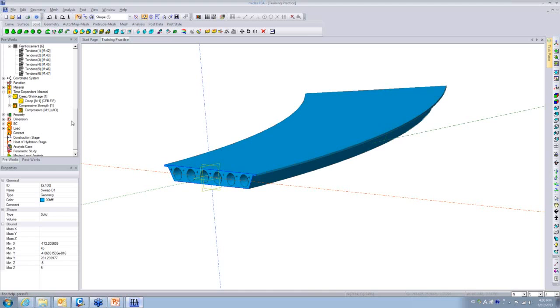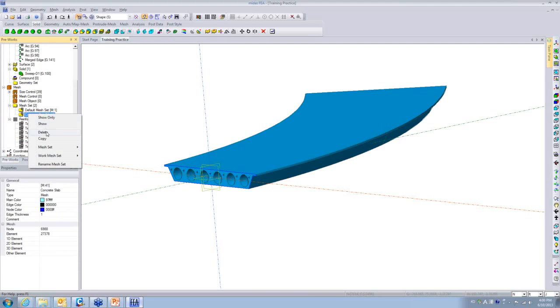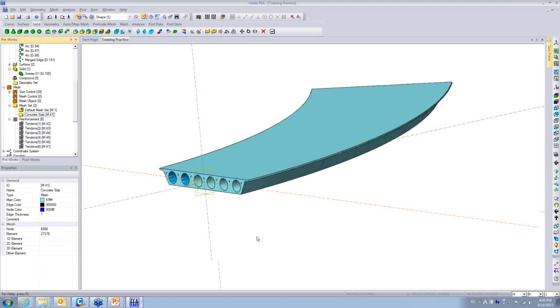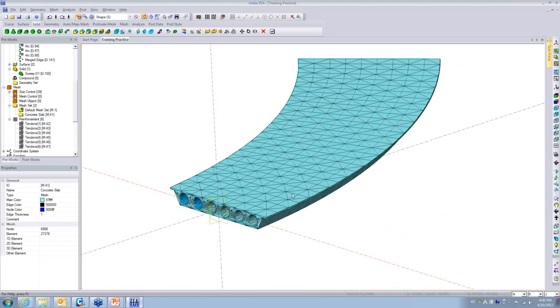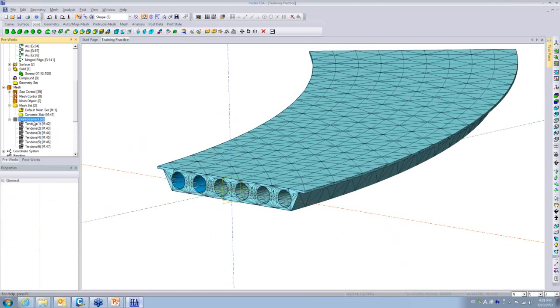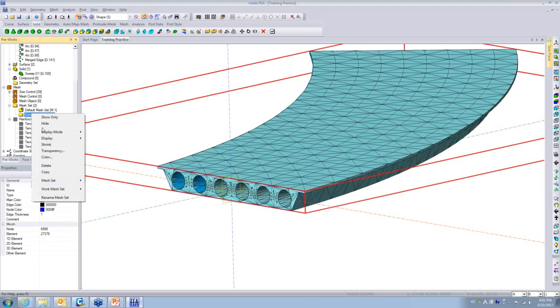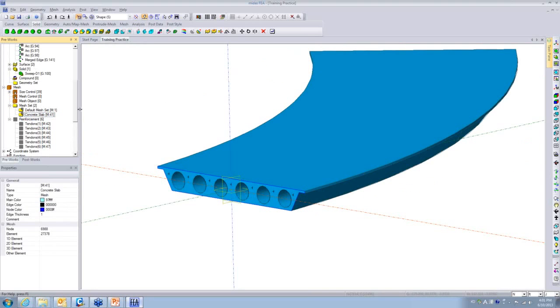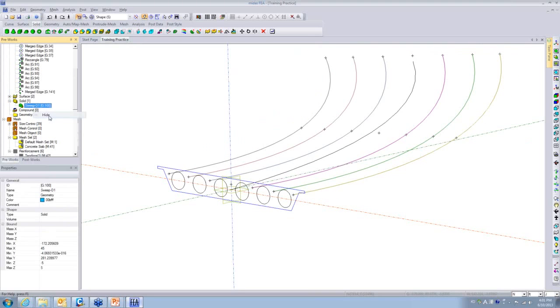All right, and if I go to the mesh parts, I can simply show you this, and you see how easily I can just create a mesh, automatic mesh, and all these circles are exactly as they are. We can simply define the reinforcement. So I use the reinforcement and define the, so if I turn the other ones off, you can see this better. All right, so these are the tendon profiles. I assigned the pre-stressing, post-tension tendon property to that. If you want to define any linear or non-linear material, you can define for that.